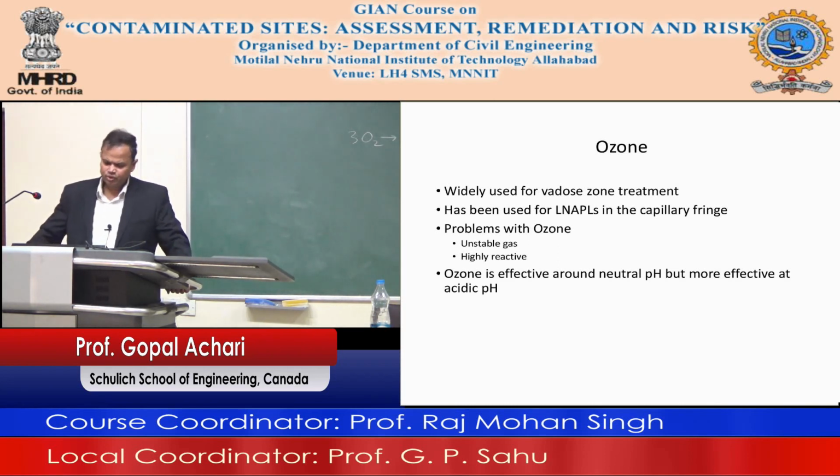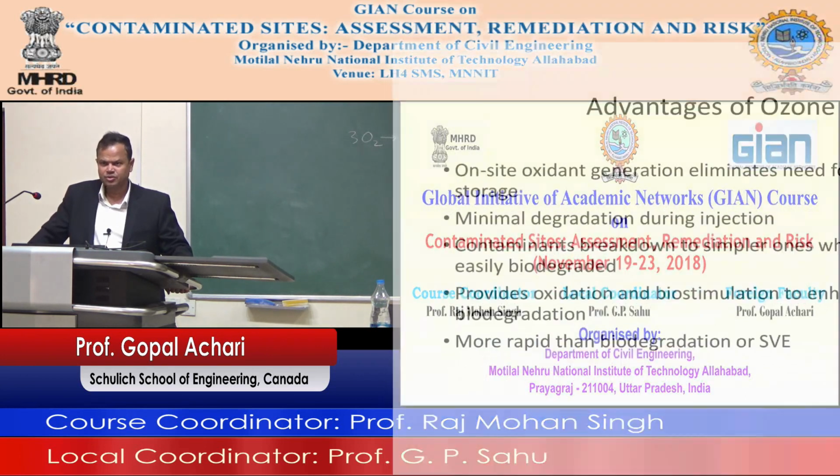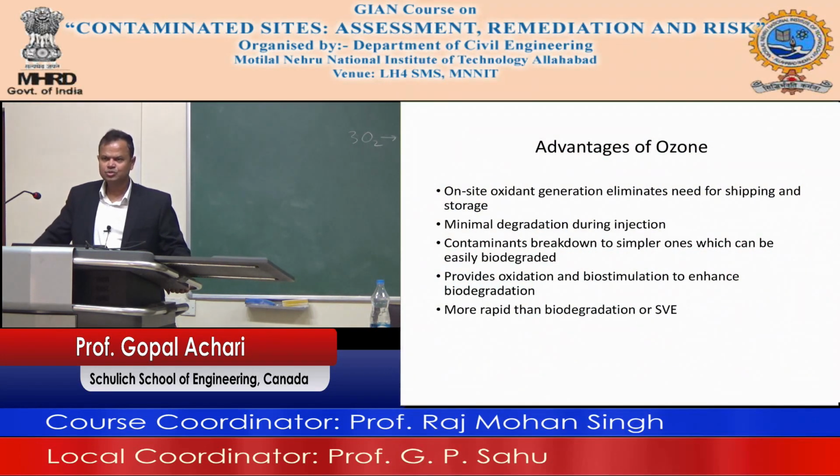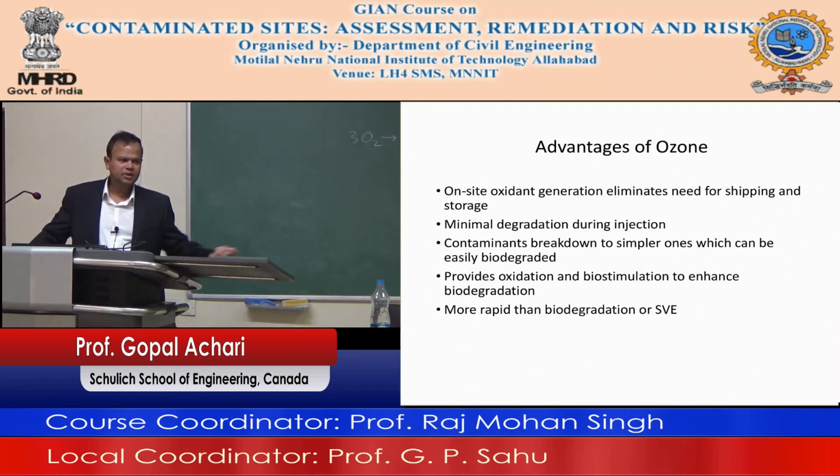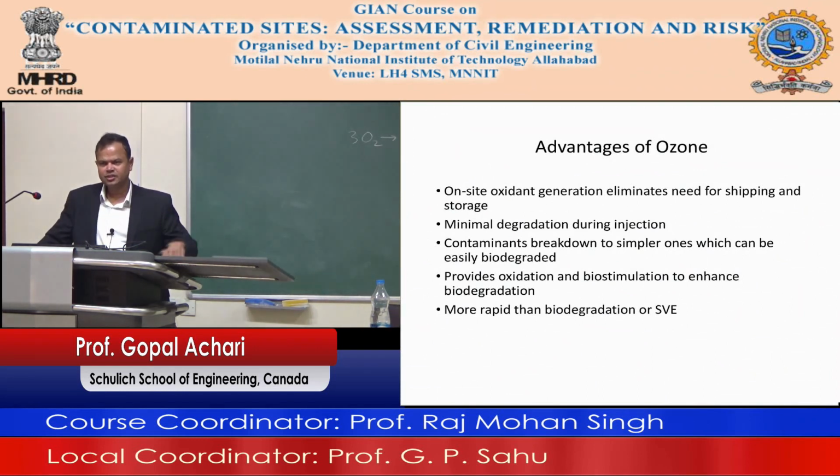The advantages of ozone: on-site oxidant generation eliminates the need for shipping and storage. You bring your ozone generator. It's innocuous if you don't generate it. The moment you want it, you plug it in, you generate it, you do your thing, and then you unplug it and you go home. There's minimal degradation during injection.